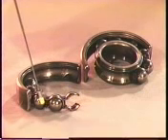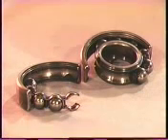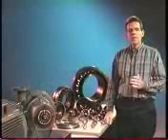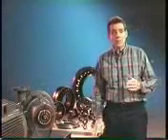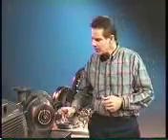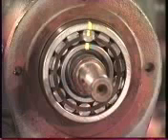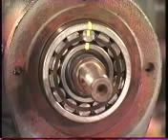the balls or rollers. Let's take a look at how these can be approximated using an actual bearing on a shaft. The defect frequencies are often expressed as a multiple of the turning speed of the shaft. That is, for each revolution of the shaft, how many impacts will be made due to a particular fault. This bearing has been marked so we can visually determine the approximate frequencies.